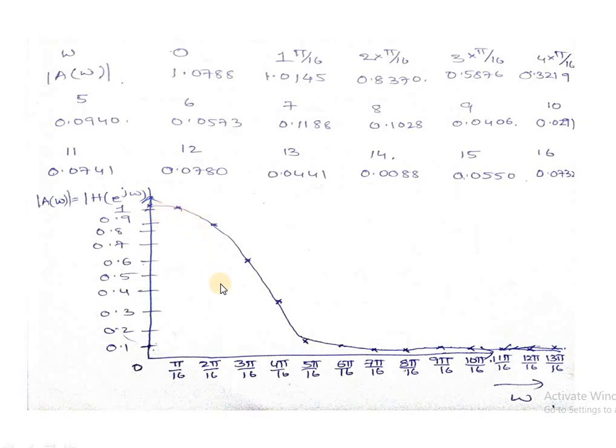And I was able to see the frequency response or the magnitude response of the linear phase FIR filter that we have designed so far. In this case we are able to see that it is monotonically decreasing, and you are able to see that the values of the filter are all non-zero values in the stop band too. This is what we are able to observe.